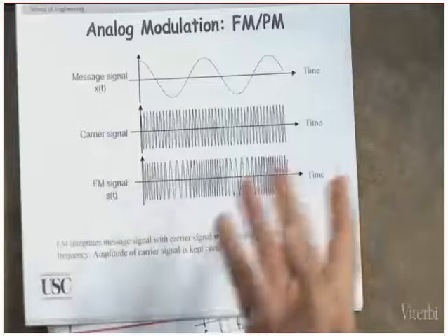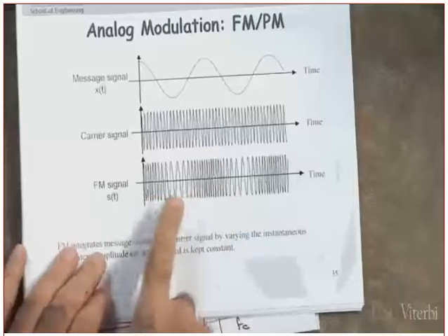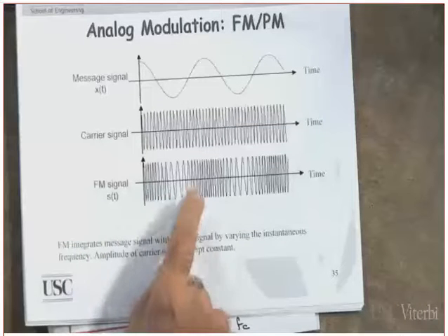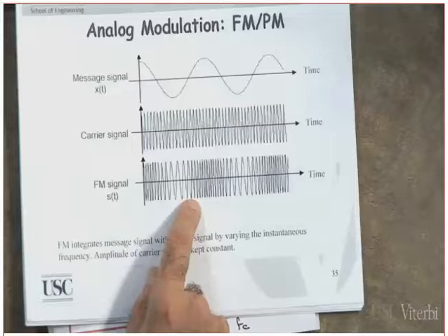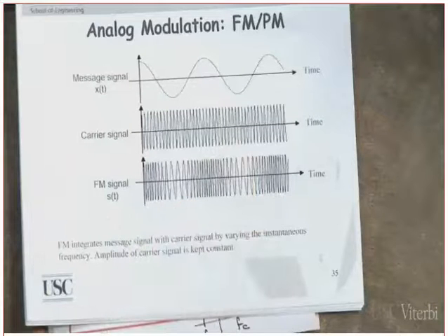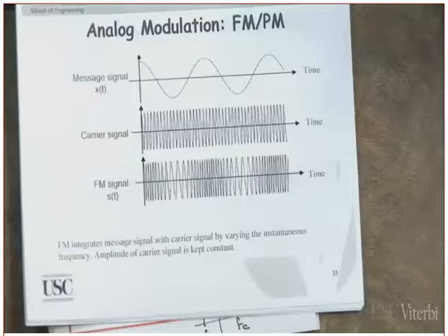Analytically, if you do it analytically, you will be able to tell. But by just looking at it, you cannot. But you can see that the amplitude is not changing. True or false? True. What do I call this type of modulation technique? Constant envelope. Question. In reality, when you are transmitting an FM signal, will the amplitude be received constant, or will there be some fluctuations? There will be some fluctuations because of what I told you about a moment ago, the attenuation, the fading, and all of these things.